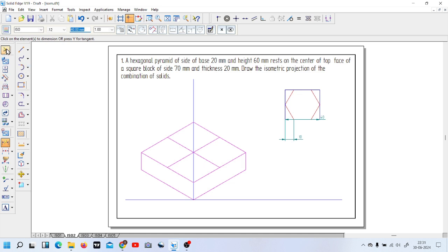Is it 40 mm? Over length here it is 40 mm. Okay. So edge distance is 20 mm. So now I am drawing the entire drawing as per scale, and finally I am going to reduce it to 0.8163 times. So you are going to get isometric projection. Okay.